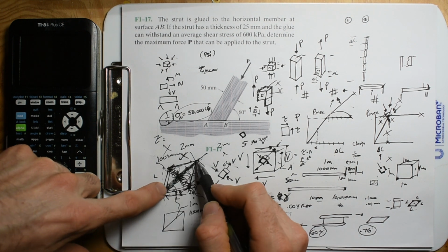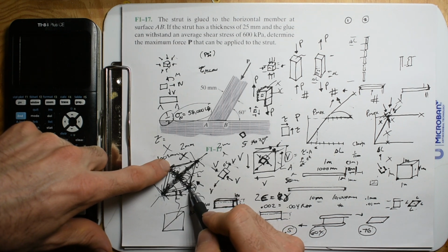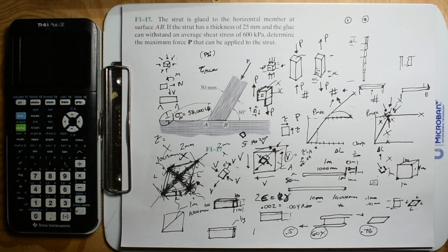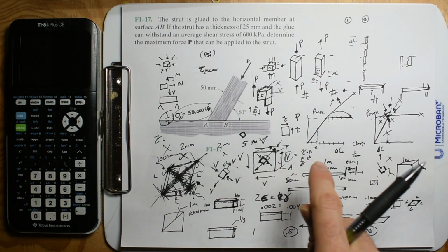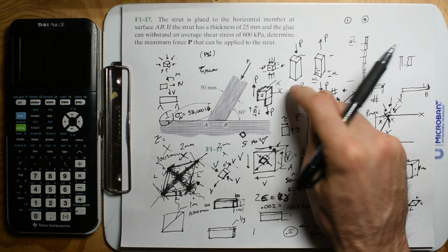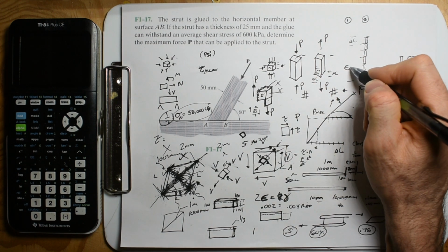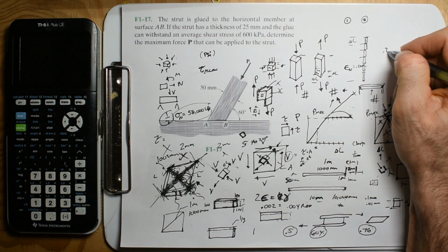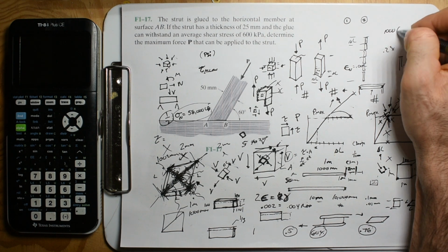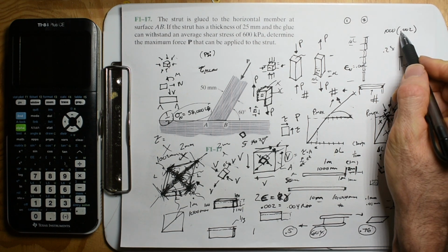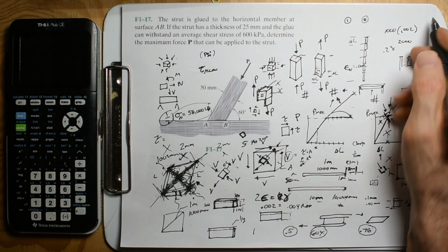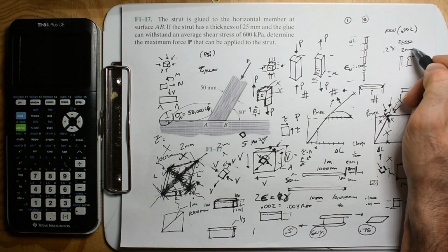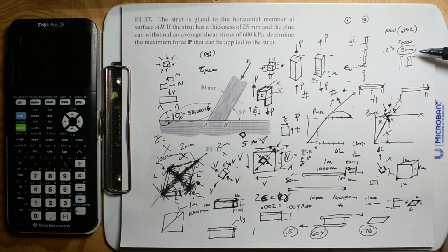So if this length gets too long, or this compression... this is fascinating to me, because steel can lengthen and compress the same amount. Its normal strain, its axial strain, is 0.002, which is 0.2%. If I have 1,000 times 0.002, I just move the decimal: multiply by 2, that's 2,000, and then move the decimal place 1, 2, 3. That's how I get that 2 millimeters. So that's a good one to show.